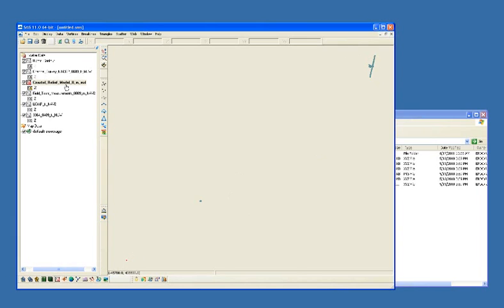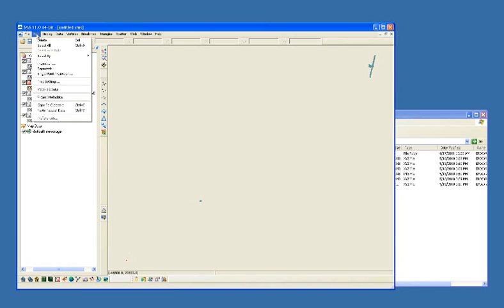So what I'm going to do is, for this coastal relief model, the very first one that's down here, we know that's in geographic coordinates. So the first thing that you should do, under Edit, is come in and look at the projection, and that's not reprojecting anything. That's setting what you want the data to end up in.